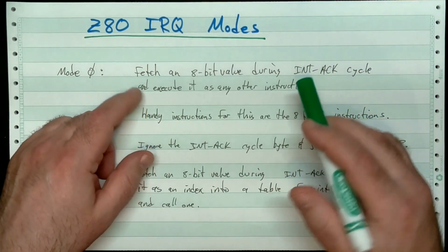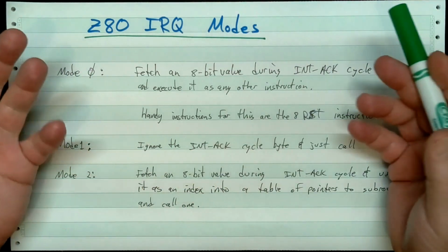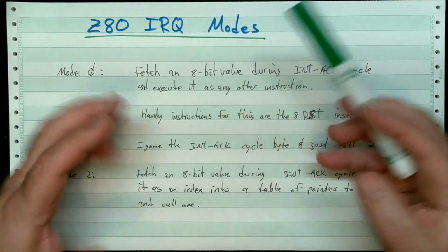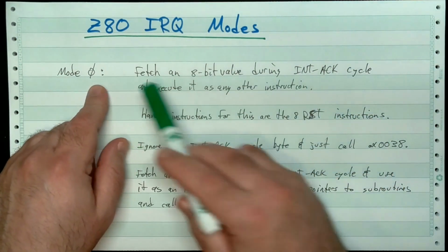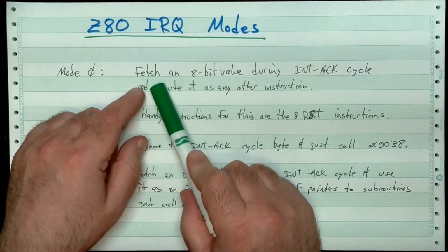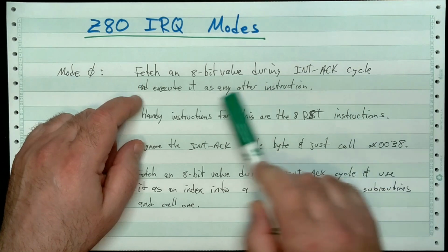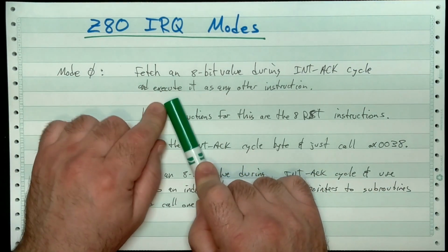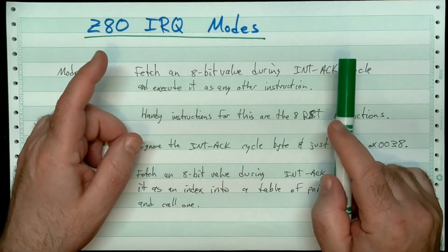This is all well known. Nobody would use the 8080. That's why Intel themselves came out with the 8085 and so on. Well, anyway, some engineers left, created the Z80. That's why we have these modes. Mode 0 is 8080 compatibility mode. And the way this works is that during that M1 cycle, it reads that magical byte that we just looked at, and it simply executes that as it would any other instruction. That's all there is to it.